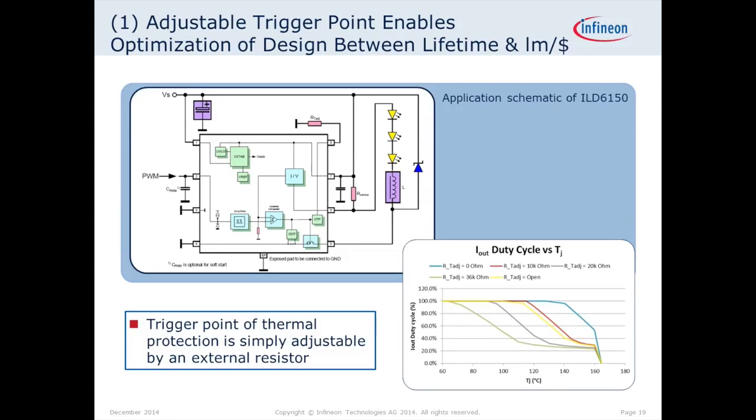Let's come to the advanced thermal protection. Here we are talking about a new generation of LED driver ICs for up to 60 volt breakdown voltage. The same is valid for these LED driver ICs as mentioned before. They can be used as a thermal sensor, so no NTC required, if they can be thermally coupled to the LEDs. And also there's a slope function which protects not only the IC but also the LED system. But in addition, there are a few more points which I would like to present to you.